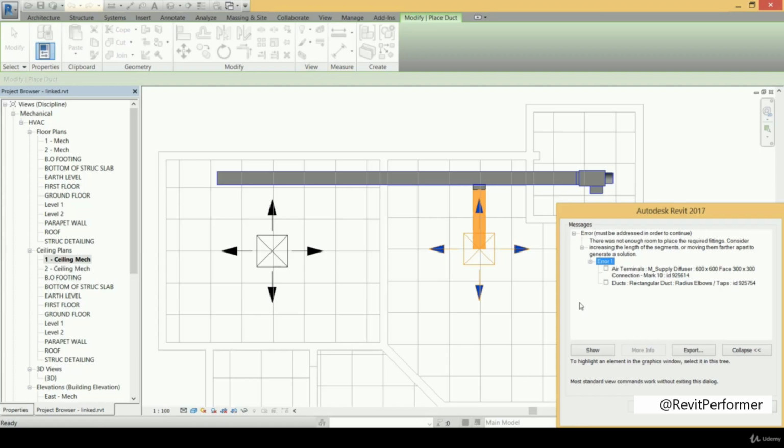And this is because if we need to connect the branched duct to the air terminal, we use an elbow, so that elbow must have a specific radius, as we learned before. But when the vertical distance is small, the elbow cannot be installed, as the elbow needs a larger vertical distance to be curved, or to take its sufficient curved shape.